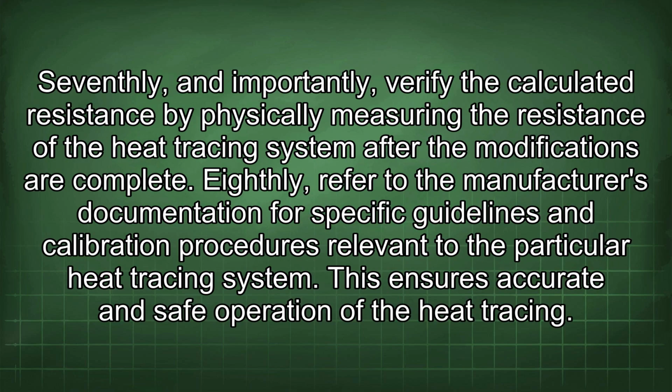Seventhly, and importantly, verify the calculated resistance by physically measuring the resistance of the heat tracing system after the modifications are complete. Eighthly, refer to the manufacturer's documentation for specific guidelines and calibration procedures relevant to the particular heat tracing system. This ensures accurate and safe operation of the heat tracing.